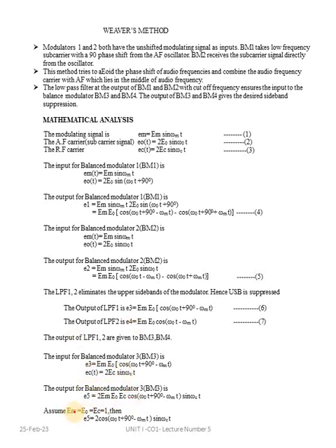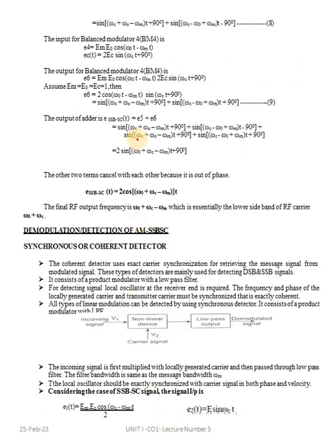Assume E_m equals E_out, that is the output voltage, equal to 1. Then E5 is equal to 2 cos (omega_0 t plus 90 degrees minus omega_m t) into sin omega_c t. So the input for balanced modulator BM4 is written like this. While combining BM4 and BM3, we get the output equation as 2 sin (omega_0 plus omega_c minus omega_m plus 90 degrees). The other two terms cancel each other because they are out of phase. So we get 2 into cos (omega_0 plus omega_c minus omega_m) t.